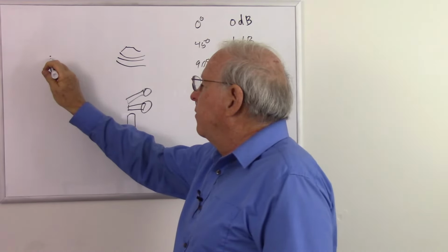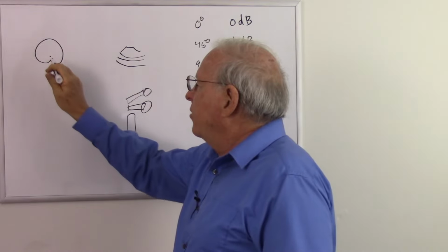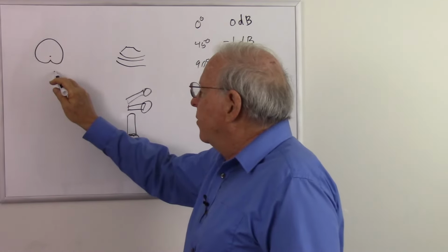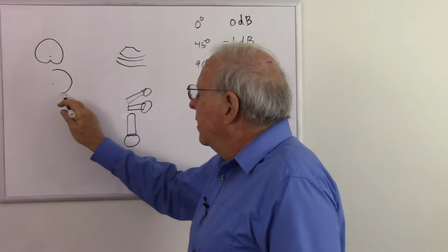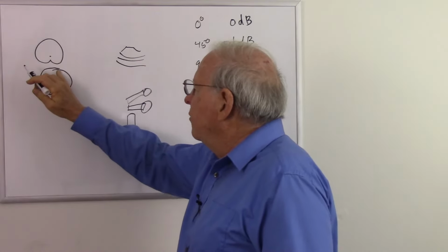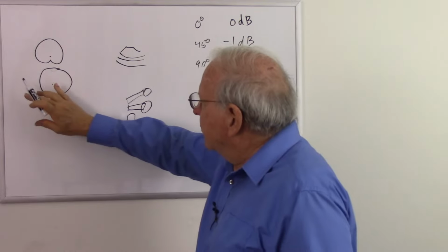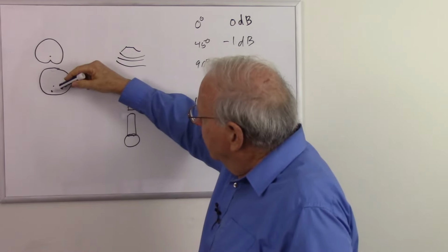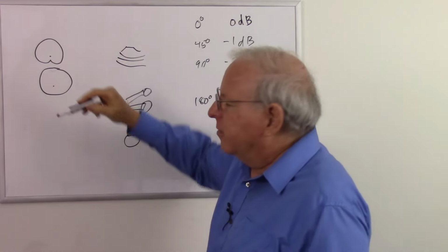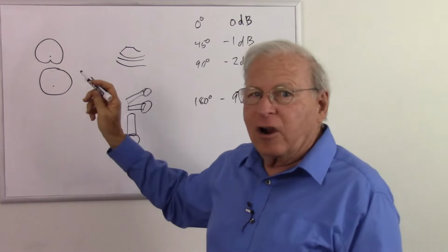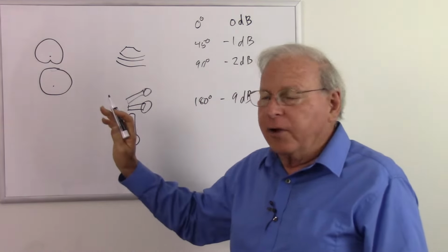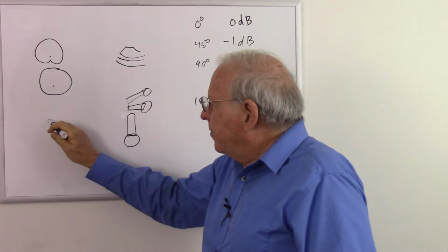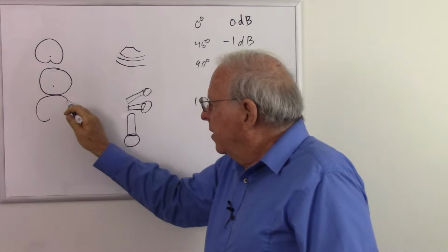So there's our microphone. The cardioid has a shape or a pickup pattern, something like that. If it has more sensitivity to the back than this one, it has a shape more like, okay, is that a good drawing? Good enough. Notice that I'm just going to move my little dot to right there. So it's almost a circle, and notice it's less sensitive to the back than to the front, but not quite as drastic as the cardioid. That's called a subcardioid.